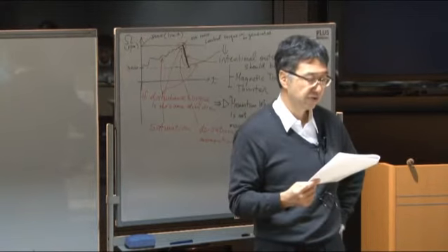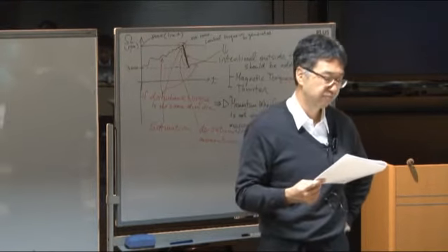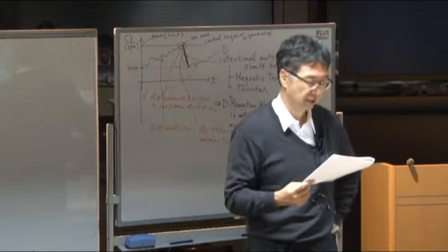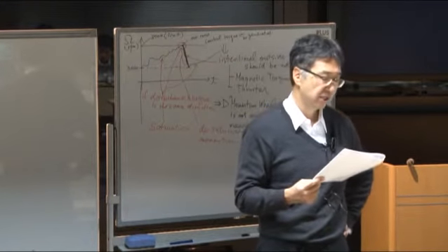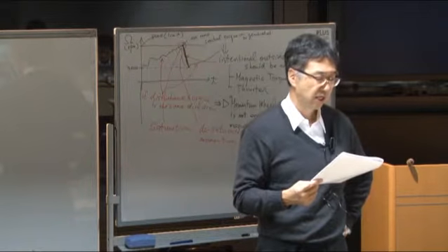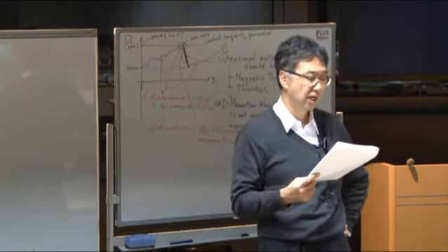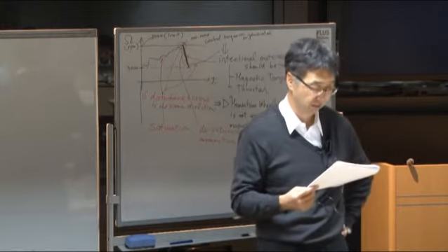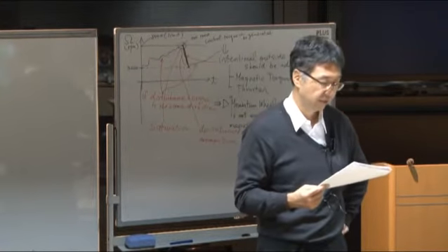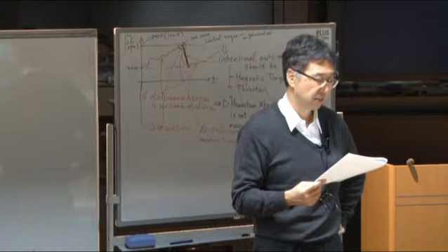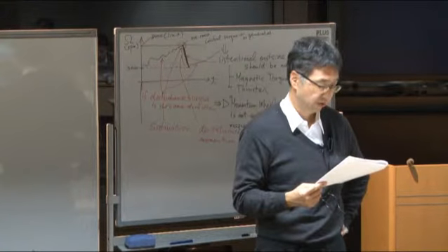Okay, and the first three satellites are spin satellites, single spin satellites. In the single spin satellite case, the moment of inertia around the spin axis should be the maximum, as I said. Otherwise, the spin axis will change.